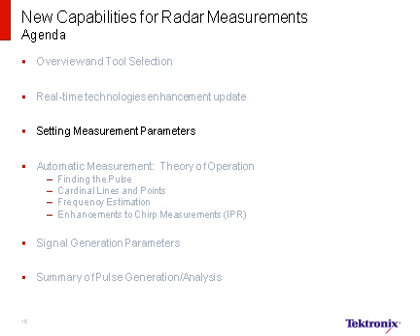From a test and measurement standpoint, it is always easier to create a known signal than measure something unknown. So we'll spend a little bit more time on setting parameters and analysis of unknown signals. Since automatic pulse measurements for radars must cover a wide variety and types of pulses, it is important that some signal conditioning parameters for the expected signal of interest are set for the most accurate and meaningful measurement results.